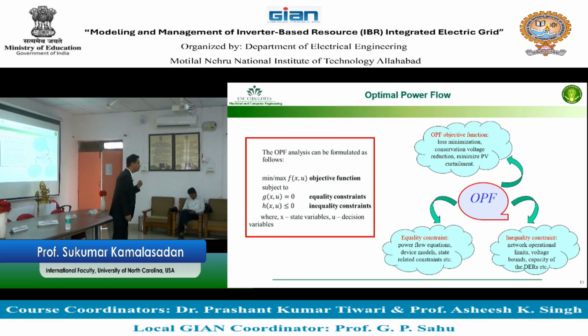One is perfect, but you have a band, you can go from 1.05 to 0.95, right? So where do you operate? You operate on the boundary of 0.95 to get the better bang for the buck, meaning losses, or you operate at 1.05 so you have the room. Yes, you have to operate a little lower, and if you operate the voltage lower, that's the best way that you can maintain. So that doesn't mean you cannot hit 0.95 because there's a change associated with it.